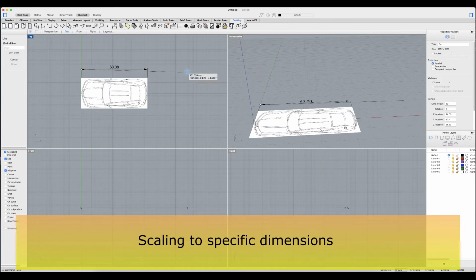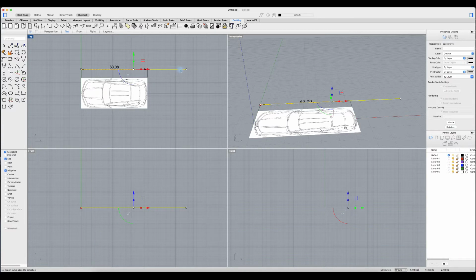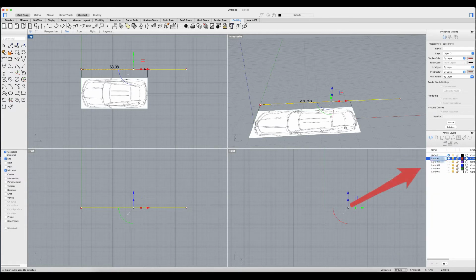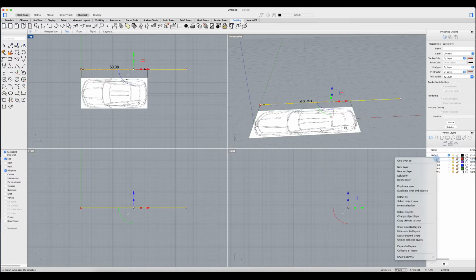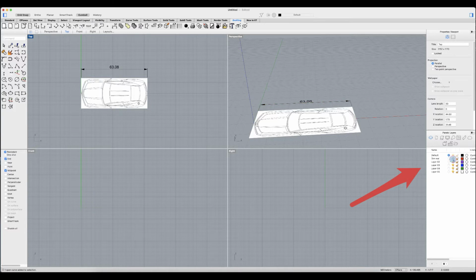and let's say I wanted to do 100. I'm going to use my line tool, establish a real dimension. This is 100. What I want to do is move this into a separate layer, and let's just name this layer dimension real, and I'm going to right click, change object layer. And if I toggle the light bulb on and off, it's now currently in the layer dimension real. I'm going to lock that down.